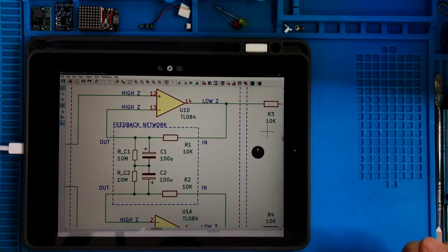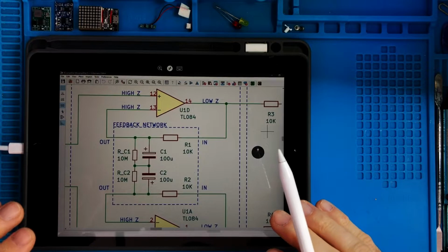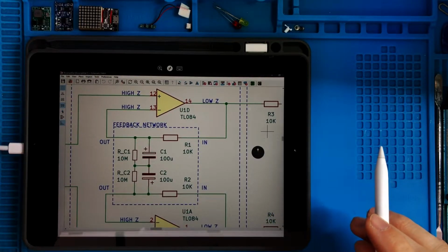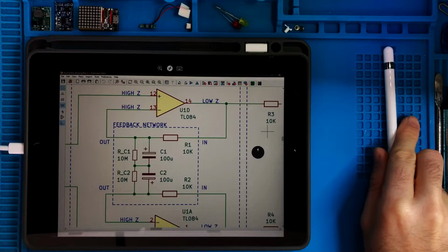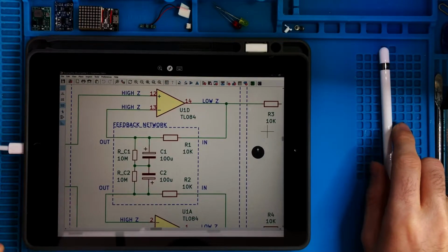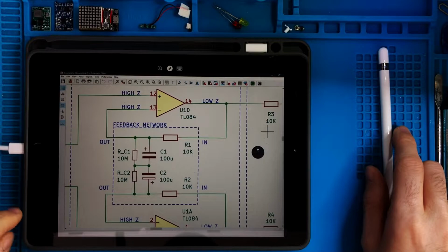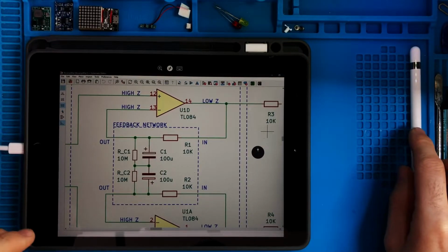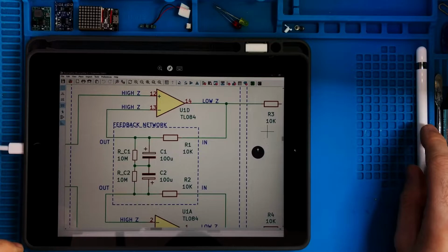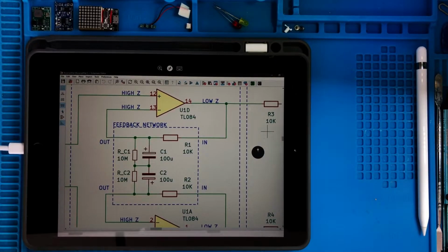So these are tricks that we have to know, and this is the reason for which when you simulate something, you can't normally expect to simulate exactly the circuit you have mounted, because the numerical algorithm cannot work with infinite numbers. So then the question is, but how can the circuit work? Can the physics really work with amplification factors that are extremely high, that tend to infinity? The answer is not really.